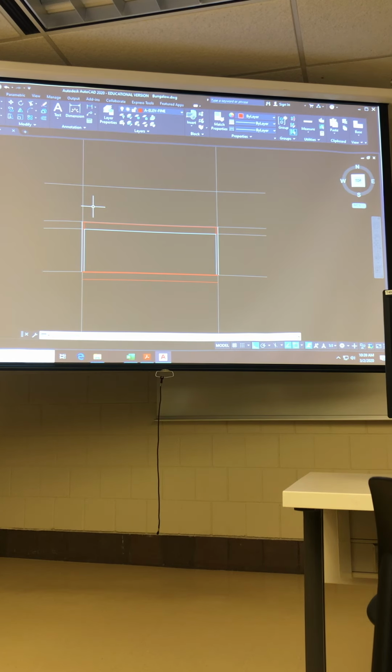So I'm going to go back to my drawing, and I'm going to offset 3 feet 9.5 inches from the bottom of my truss up to that work point, and that happens to be right here.